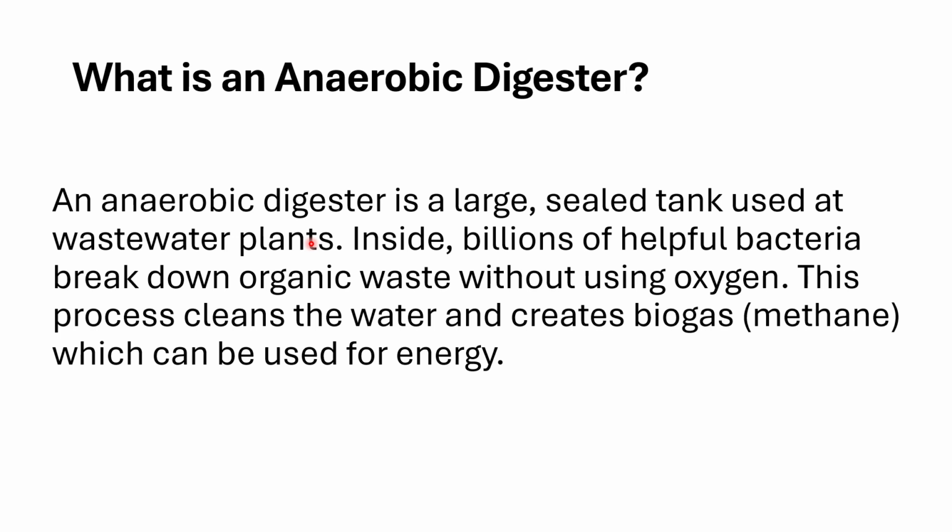We're getting rid of that organic stuff, separating the sludge from what's called a supernatant, which is a wastewater liquid mainly that's going to rise to the top of the tank. And we're going to decant it or get rid of it in this digester. So the process is going to clean the water, but here's something else that it does. It creates biogas. Hydrogen sulfide and methane.